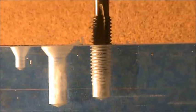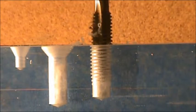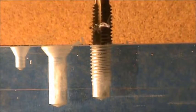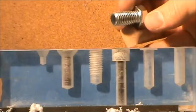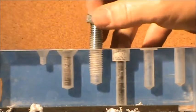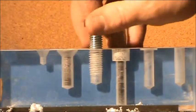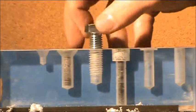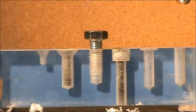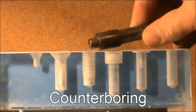As we can see, we reverse the tap back so the chips will follow the thread to go back out. Usually the tapped hole is longer than the fastener. This enables the fastener to fit in the hole completely.